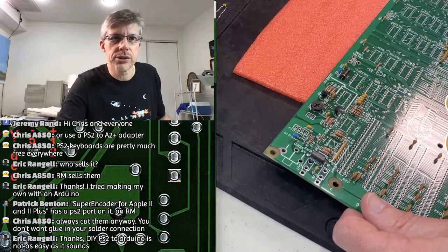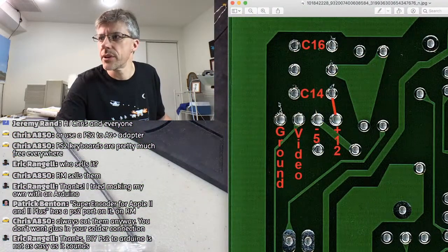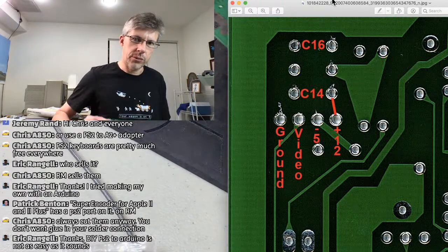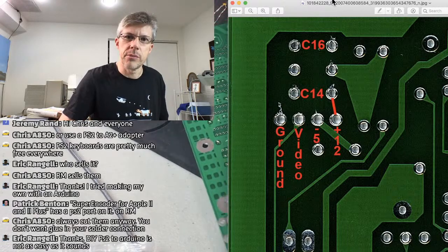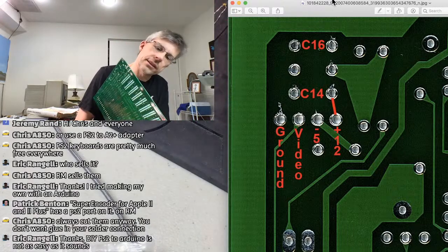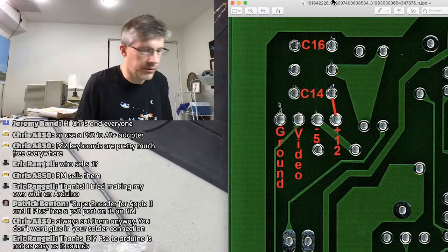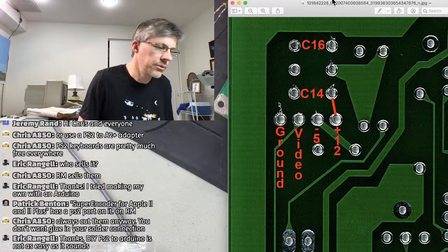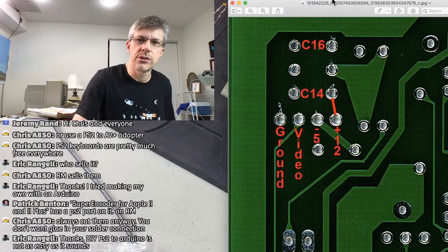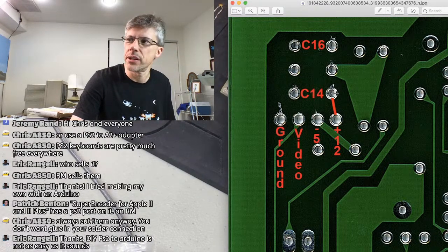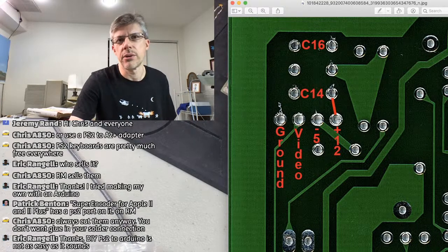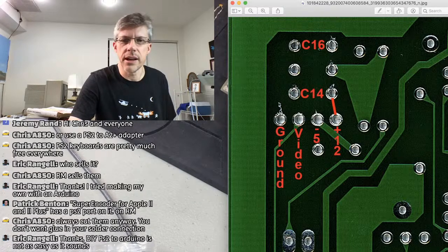of what that should look like, and let me move this into the frame so you can actually see it. This is actually the back of the board, so we're going to flip it over, and you won't be able to see it until I move that picture out of the way. I haven't actually looked that closely at this myself, so I'm just sort of eyeballing it here. But basically, we're going to put in a capacitor, and we're going to use the extra lead of the capacitor to jump the wire from this pin here, and I'm hoping you can actually see my mouse. We're going to use that lead to jump over to the plus 12 volt for that external video adapter pin, since there's no lead actually hooked up to it.